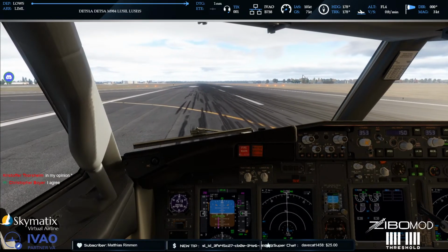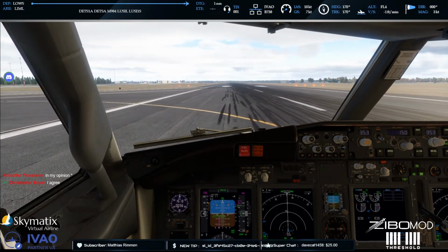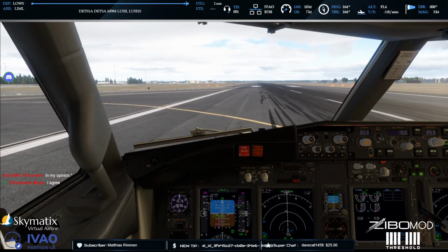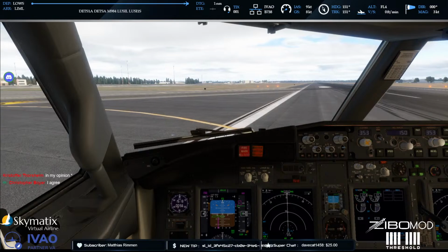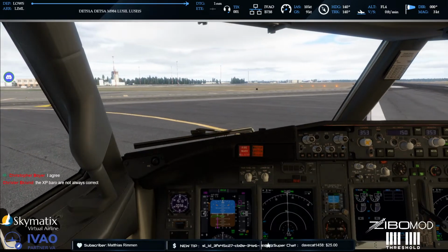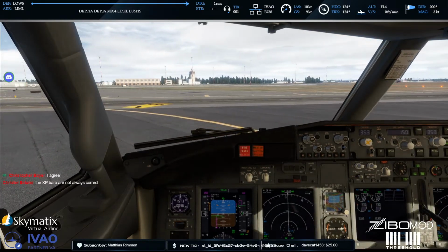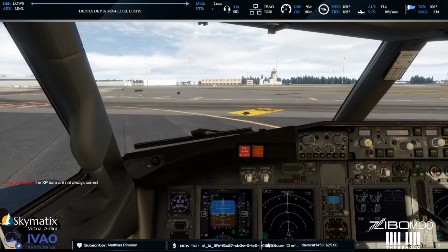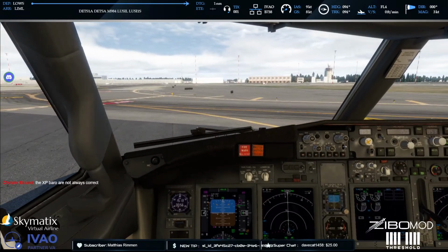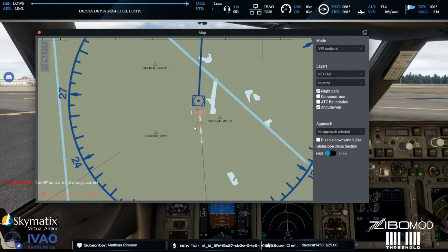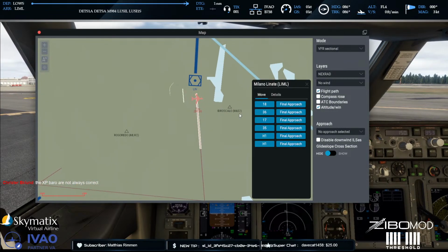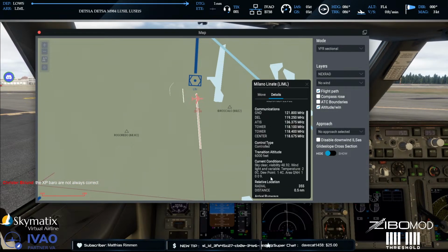And in fact, if you need to fly a localizer approach, you use VOR/LOC to get your alignment, to get aligned horizontally, and then you're going to use VNAV path to make the descent, which is going to be the mirror of the glide slope. That's why when we crossed that point, when the aircraft was supposed to descend, instead we leveled off and ended up high. And I don't know why VNAV did that.